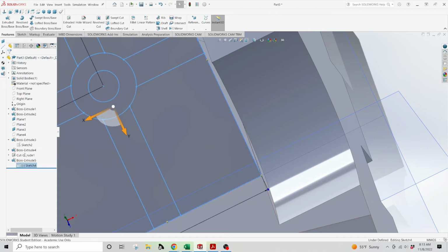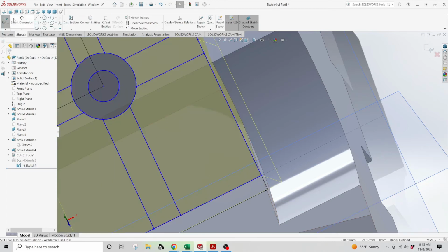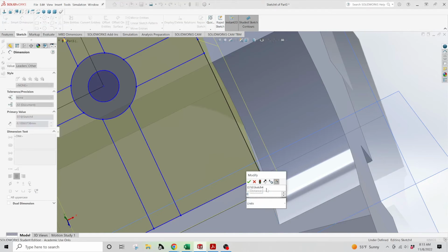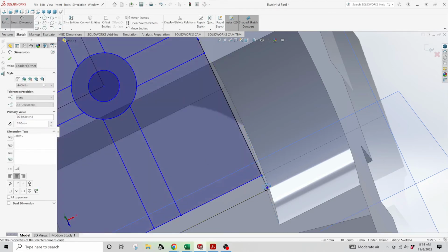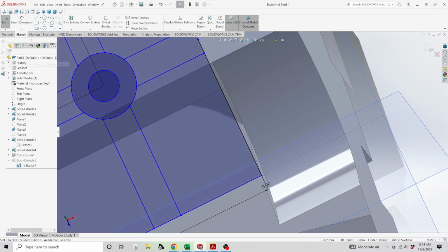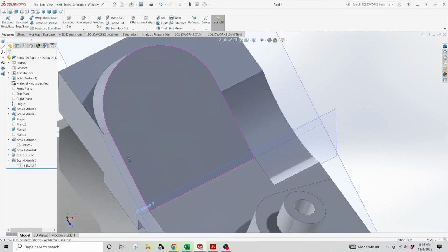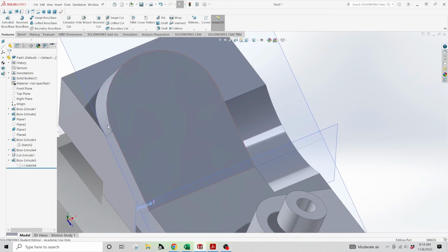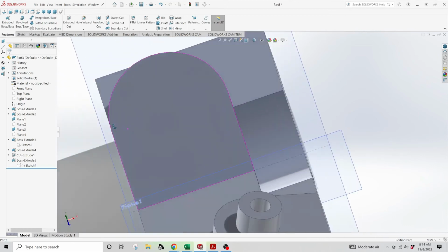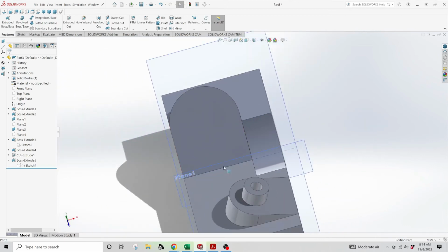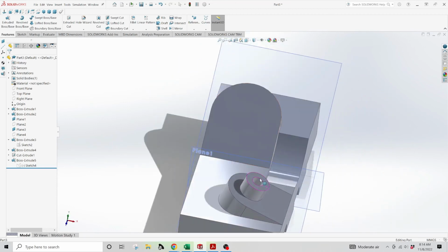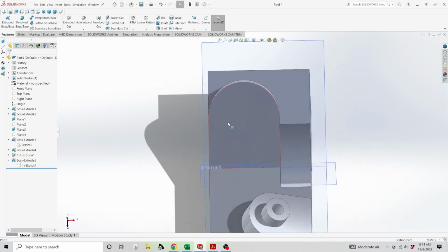So I'll make a quick edit here. Smart dimension. Distance between this edge and this one is 0. Okay. Now step out of the sketch, let it redo that. So now everything is all lined up the way it needs to be. All right. No unusual gaps, nothing weird to throw off our geometry. Now we can do our extrude cuts.